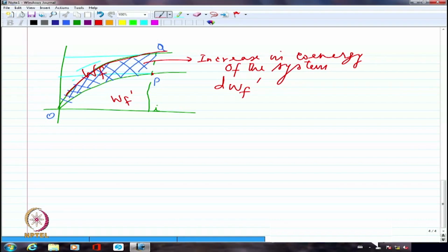At steady state, the current should not change is your perception. That is not steady state. If the initial value at the beginning of a cycle and the final value at the end of the cycle are the same, you call that steady state. Steady state does not mean it should be a constant.